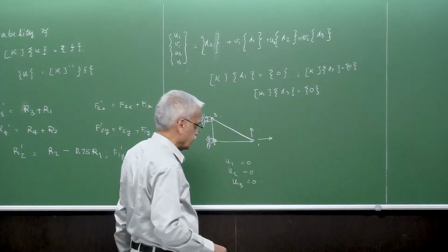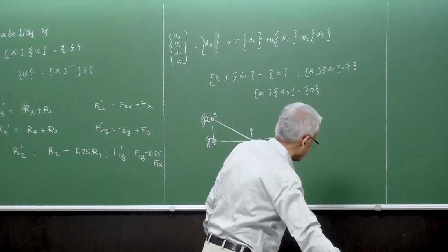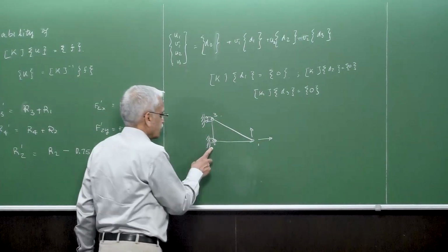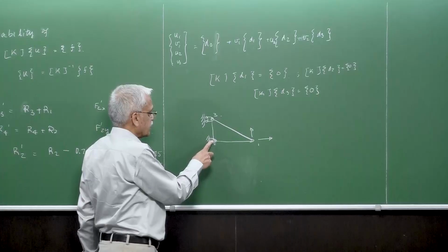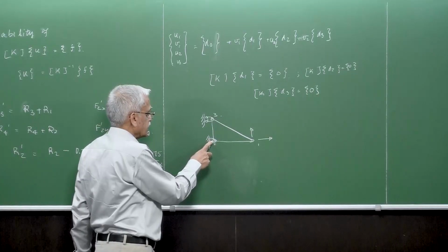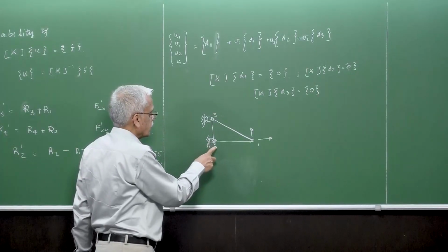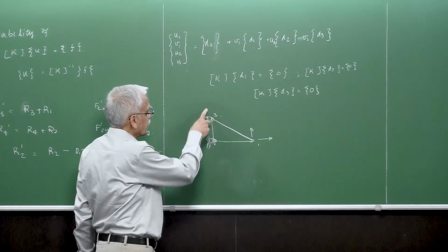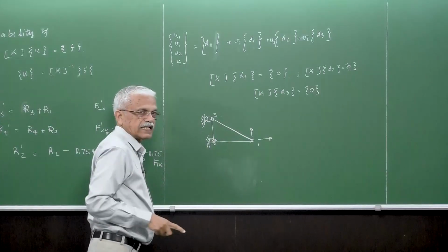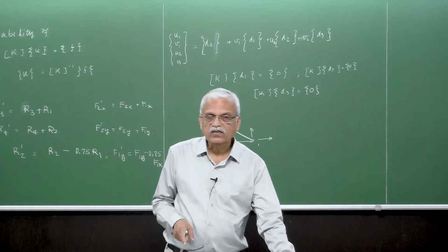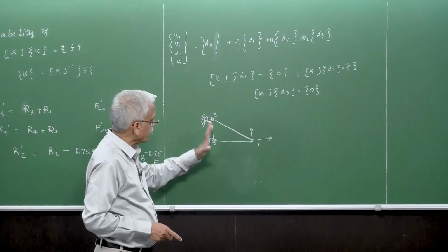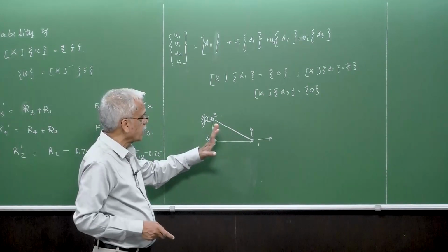What we mean is that the kind of boundary conditions we have applied here, for node 2, is a pin type, hinge type of connection, where u2 and v2 are 0, whereas node 3 can move in the y direction but not in the x direction. So these are boundary conditions which are enough to remove all the rigid body modes.